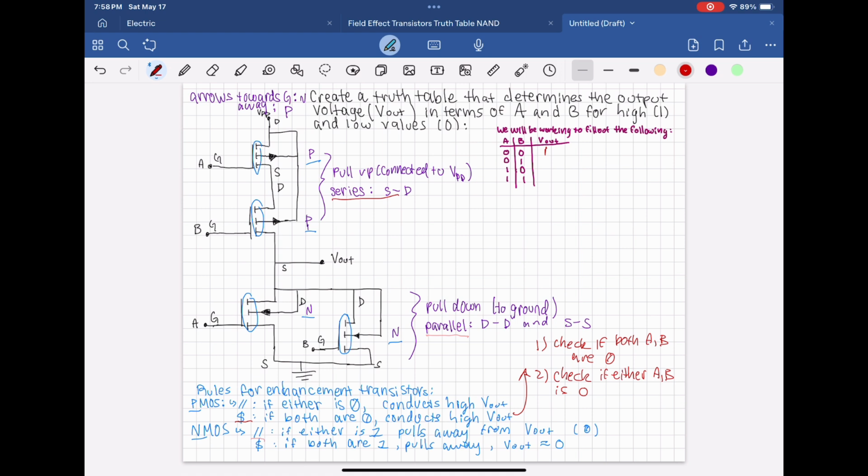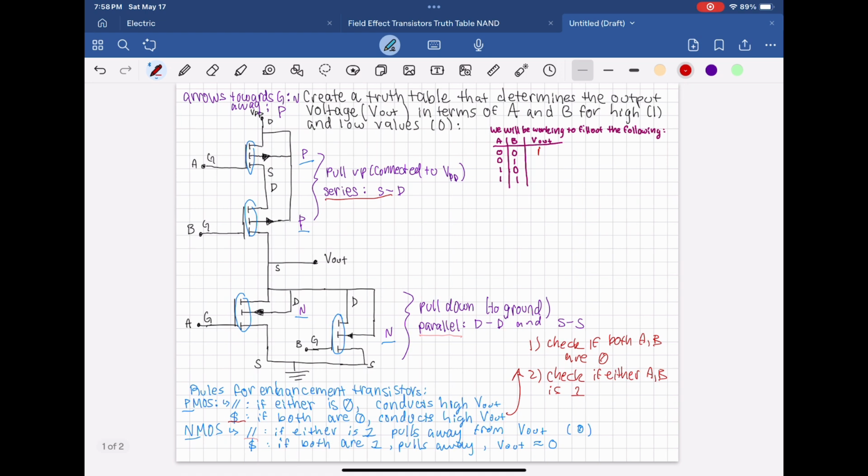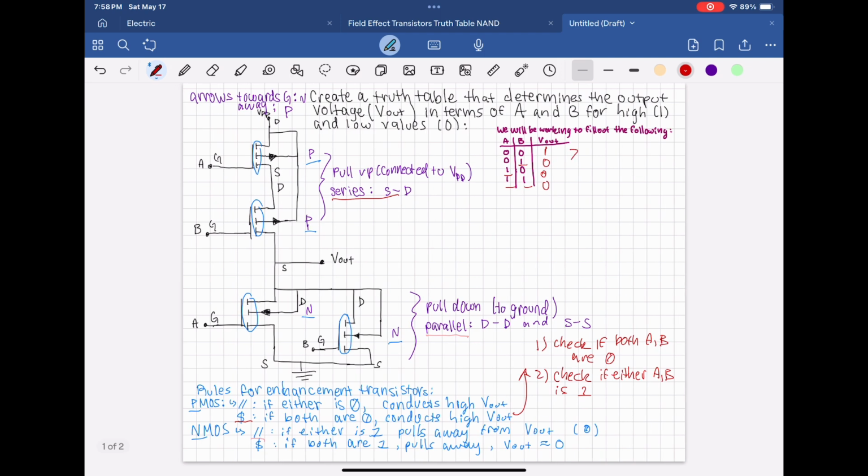So our truth table is going to look like 1, 0, 0, 0. And just as a little side thing, we can also say, interesting, we've seen this before. 1, 0, 0, 0, when 1 is in relation to A equals 0, B equals 0, is actually a NOR gate, the reverse of an OR gate, which would be 0, 1, 1, 1. You take the opposite, you end up with 1, 0, 0, 0.